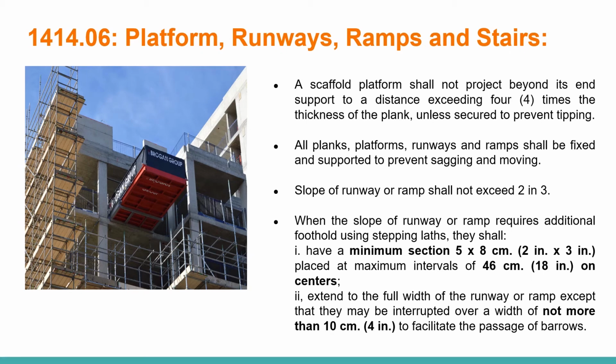When the slope of a runway or ramp requires additional foothold using stepping laths, they shall have a minimum section of 5 by 8 centimeters placed at maximum intervals of 46 centimeters on centers, or extend to the full width of the runway or ramp, except that they may be interrupted over a width of not more than 10 centimeters to facilitate the passage of barrows.